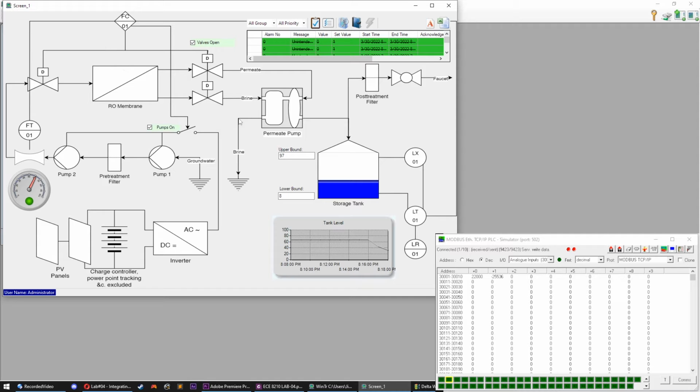And I'm not using that in the actual control of the tank level. I'm using it to verify functionality in the system. So right now you can see there's a flow. The flow is not 0, it's whatever, 60% of its maximum. And under normal conditions, that's fine, the tank is filling up. But if we want the pumps turned off, then we would expect that flow to drop to 0. I don't have anything like that simulated, so it's not going to drop to 0.